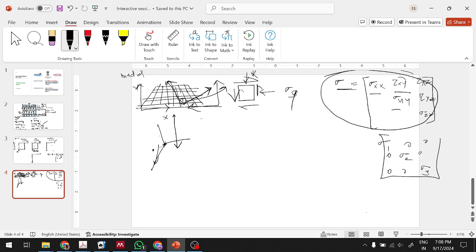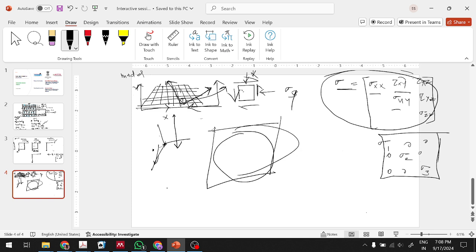That does not mean that there are no shear stresses acting on the body. It just means that there are no shear stresses acting on this particular plane along which you have now made the cross section. And then when you draw the Mohr circle, sigma n and tau, you draw the envelope and then you say that it is failing here. Then how does it have a tau here if there was no shear stress?